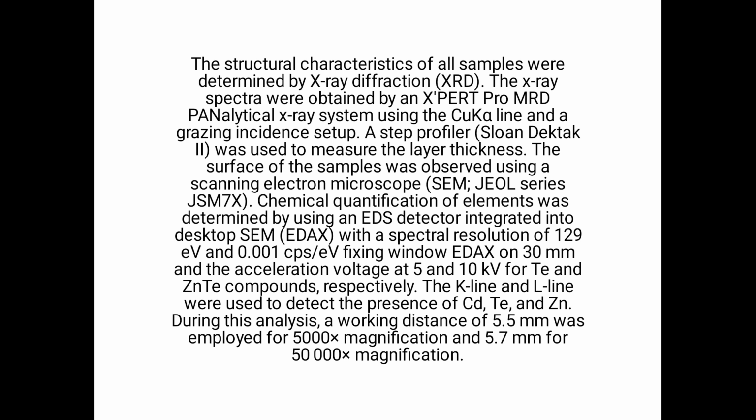The X-ray spectra were obtained by an X'Pert PRO MRD PANalytical X-ray system using the Cu Kα line and a grazing incidence setup. A profilometer, Dektak, was used to measure the layer thickness. The surface of the samples was observed using a scanning electron microscope.